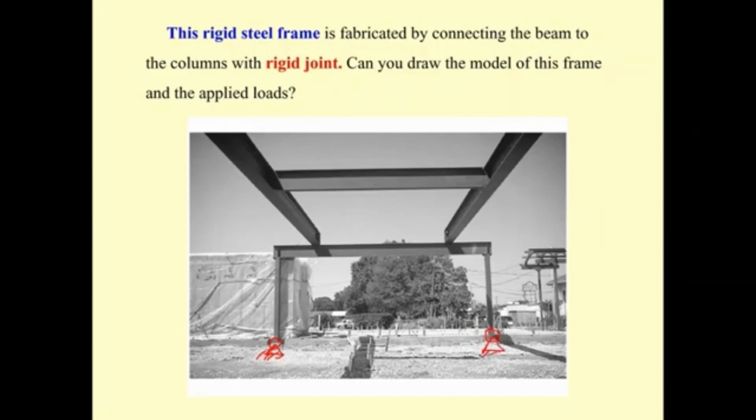And what happens is the weight of this small beam can transfer to what? To this beam. So this one is going to have the reaction here, and also this one is going to have the reaction here, and the reaction here is going to be put on the girder.